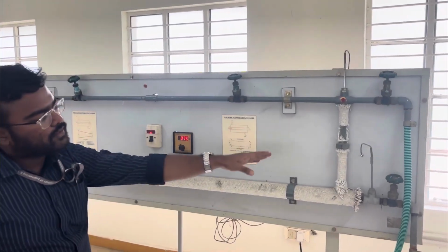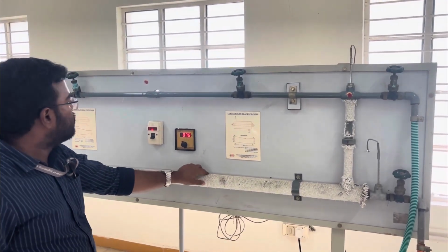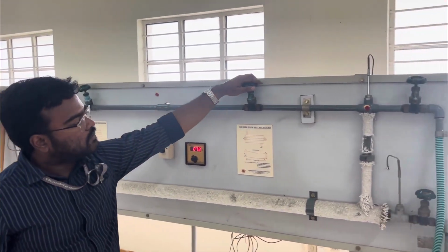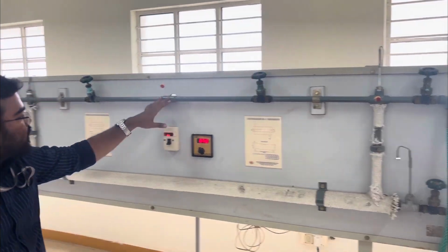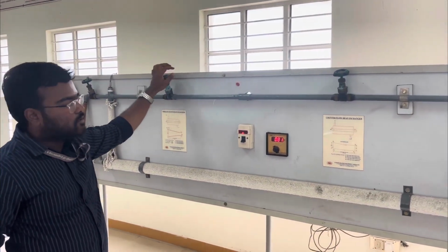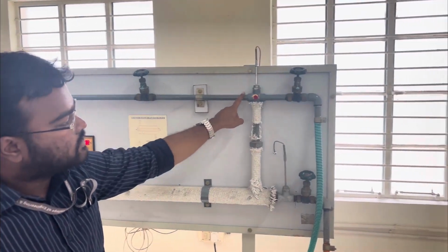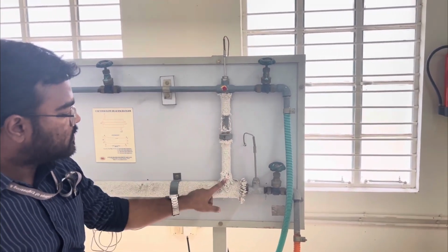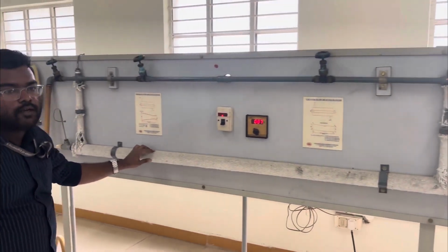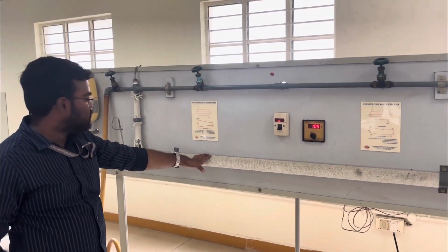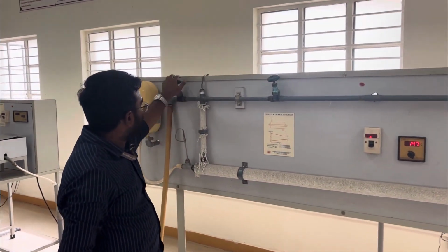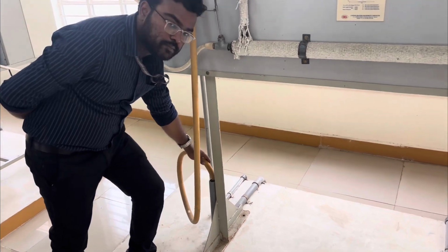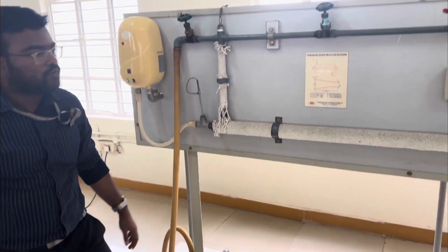The water has to travel in the opposite direction of the hot fluid. So in this case, water coming in this direction, you have to open this valve. This valve must be opened, whereas this valve must be closed, so that water enters through this direction and comes down. You have to close this valve so that water enters here and the cold fluid travels in this direction. Hence it is called a counterflow heat exchanger. You have to open this valve so that we can collect the water and measure the mass flow rate of water through this tube. So this is for counterflow heat exchangers.